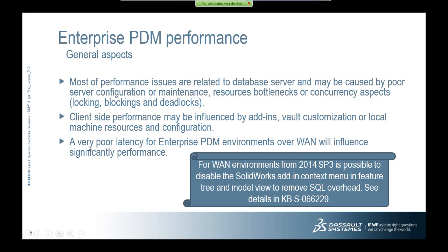Just one tip regarding a new registry key that is available from SolidWorks 2014 SP3. If you have customers that are using one environment, you can reduce the SQL overhead from the SolidWorks session by disabling some of the SolidWorks add-in contextual menu features.